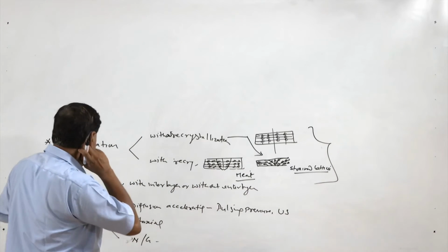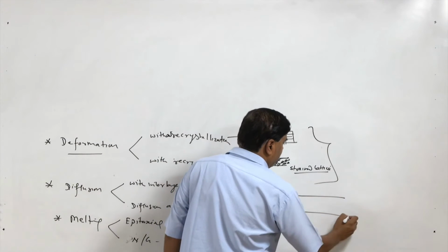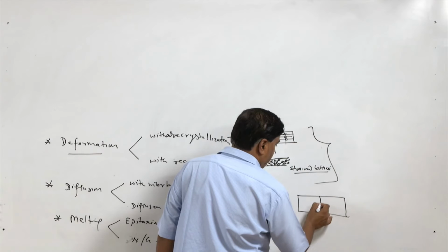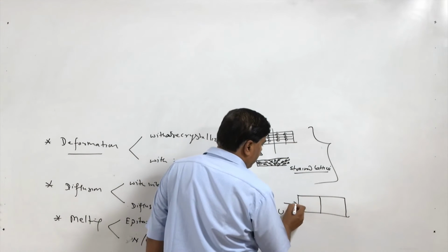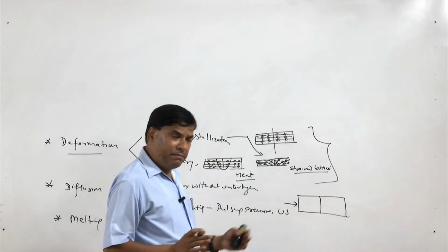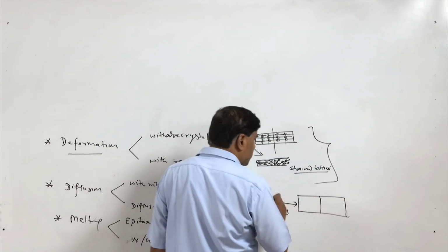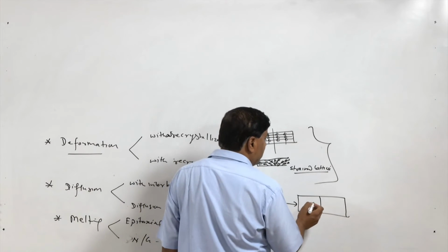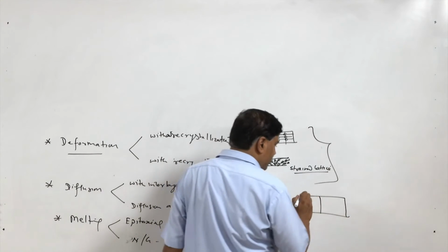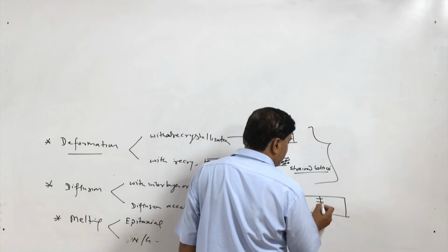In case of the diffusion, the components to be joined in very clean polished condition are brought together and kept under pressure, usually in vacuum, though it may be in an active or inert environment also. So, when there is direct metallic intimacy, due to the concentration gradient of the elements across the interface, the diffusion starts across the interface.